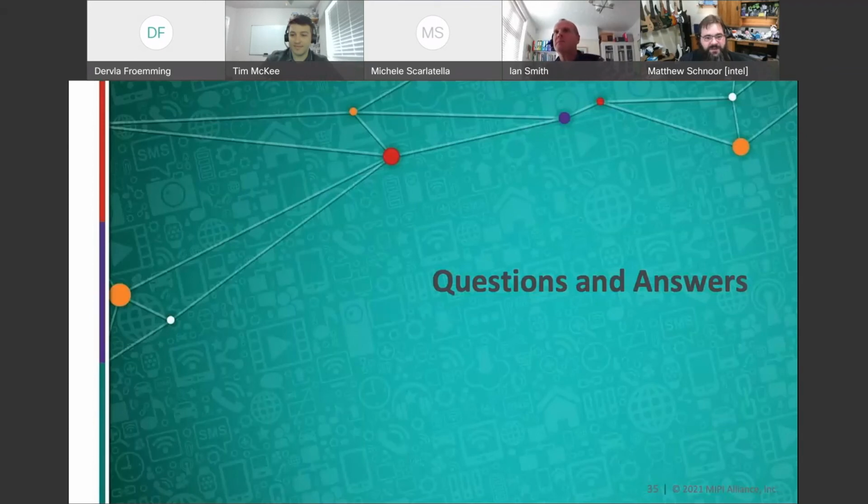So those are specified. They're in the document. They're in the FAQ. We do clearly state that clock stretching isn't allowed. This has been clearly stated. If you do need to integrate with I2C devices that do use clock stretching, you can use a bridge device. If it's a must-have and you need that on there, there are bridge devices that can probably handle that, or there should be bridge devices that can handle that.